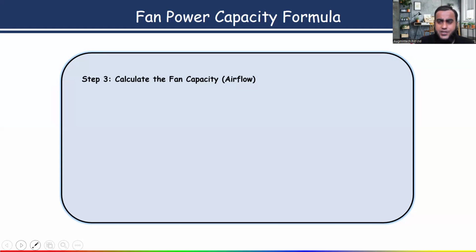Two types of ventilation are there, all of you know: natural and mechanical. Mechanical, generally, if it is a large commercial toilet area, with the help of ductwork we are extracting bad odor from each and every toilet. So in this case also, we need to do the selection of the exhaust fan.